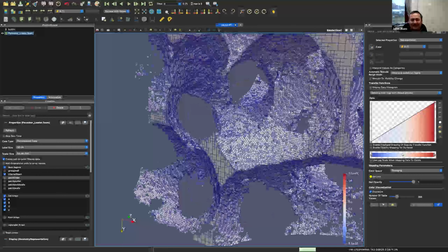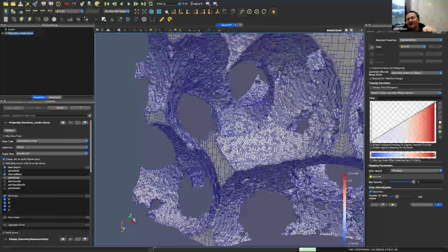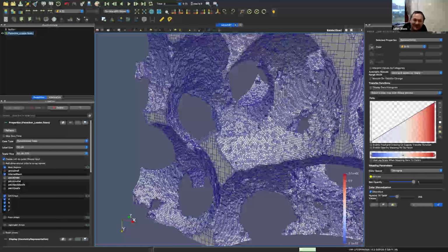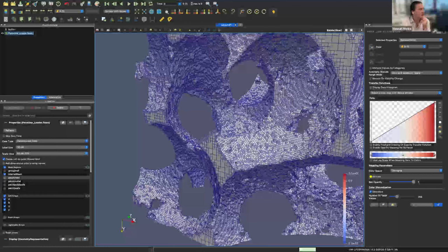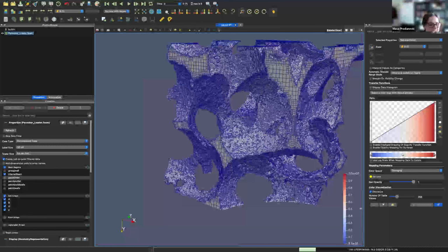Bottom line, flip your image, start over. So you can do each direction, but they always assume that it's in the positive way. It doesn't really matter for at least the first part of the tutorial, because you're just doing permeability. It should be the same in either direction. It doesn't matter if you're doing a pressure drop, but for other test cases we are doing a velocity field, and then that can matter. Solid transport can matter. Things get stuck in different ways.